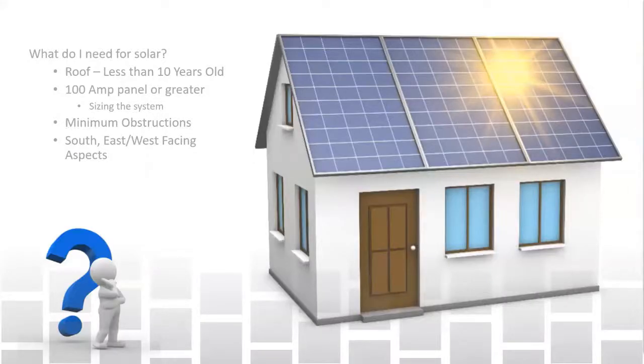Some other considerations before we jump into installation. What do I need for solar? So rule of thumb, roof less than 10 years old. This is definitely true of asphalt roofs. If you do have a metal roof, this number goes up quite a bit. Service size, we'll get into the math in a second, but a minimum of a 100 amp panel or greater. You want to be able to backfeed the maximum amount of solar that makes sense on your roof.